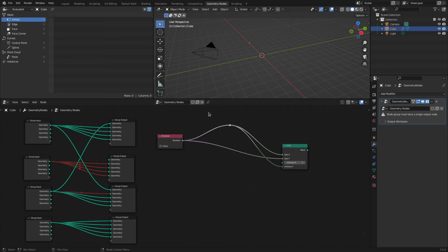The reason I'm bringing this up right now is because when you mute one end of it, so Control Alt right click drag, it is going to mute the other two routes of the link. Now, if I mute this guy here, it's just going to mute that rerouted link. Okay, if I mute the second one, now it's going to mute all of it. The whole reroute has been muted. So having done that, now if I go back over here and unmute that, it's going to unmute the entire reroute network there.